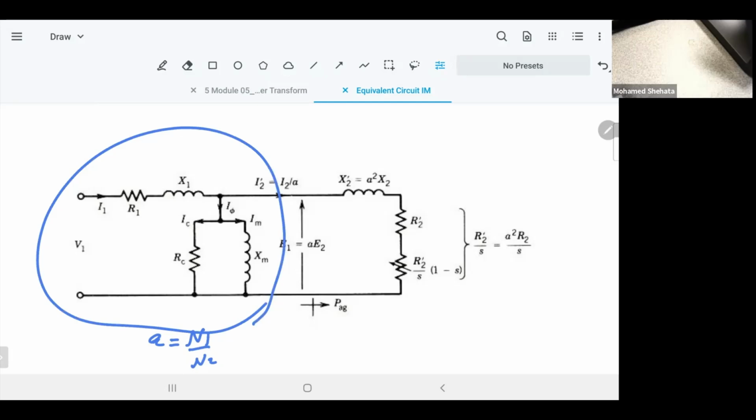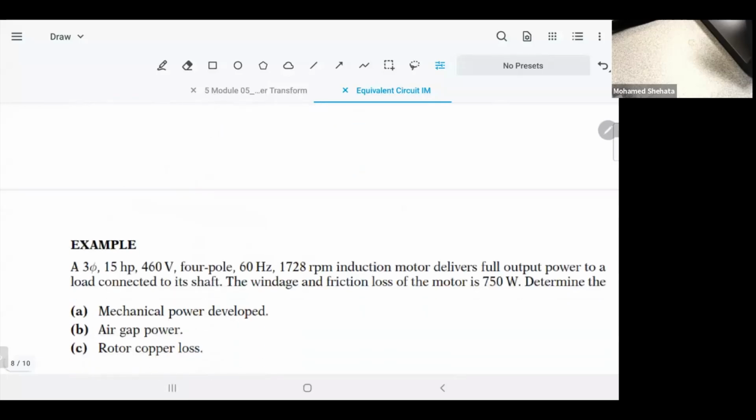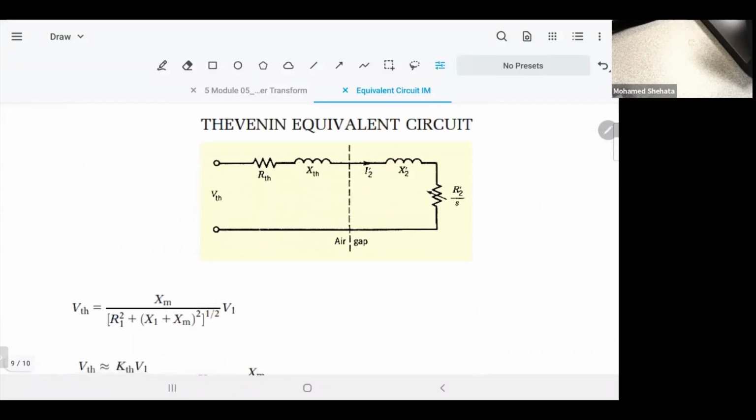The equivalent impedance using Thevenin theory. We are going to work with it and let them fight. So that will be our equivalent circuit. Nice, right? And R Thevenin is already embedded. In R Thevenin and X Thevenin, it's embedded inside the values of XM and XR and R1 and all the things. So that's V Thevenin, and that's the current I Thevenin, which is equal to I2 dash.